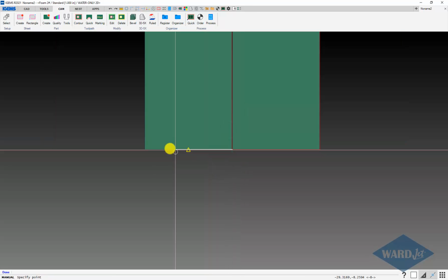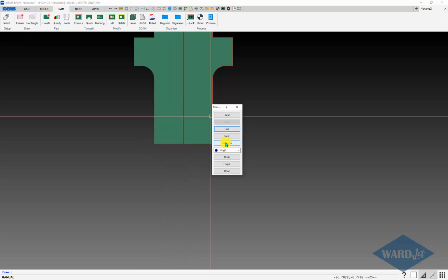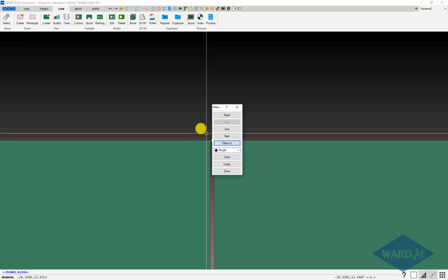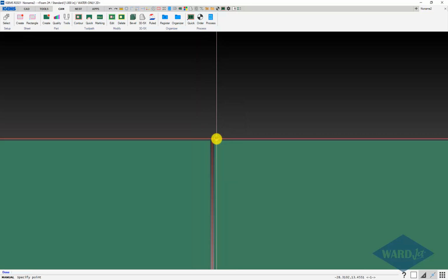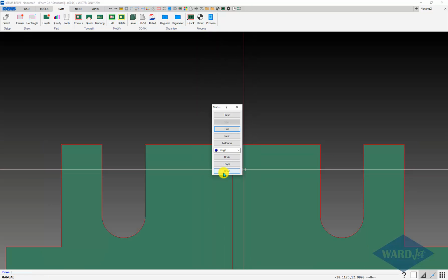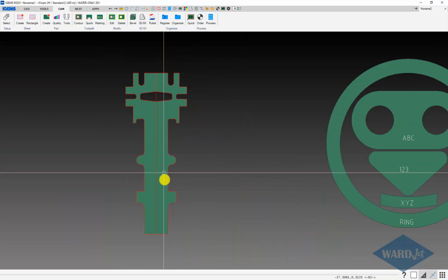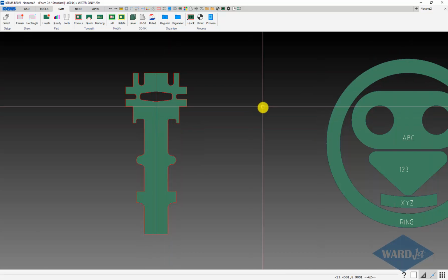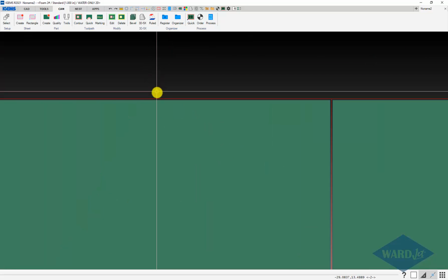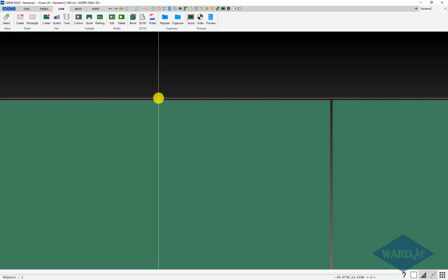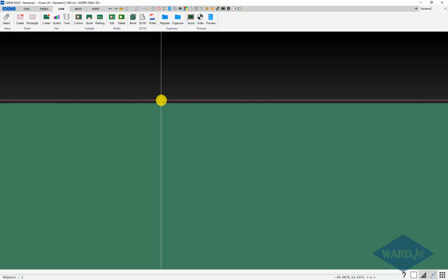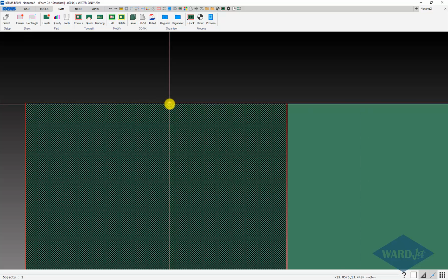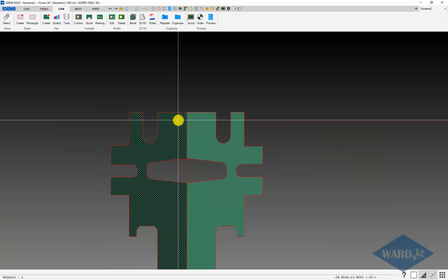and then we'll do a line, so I'll just go over to here, and we'll do follow to again, follow to up here, and then I'll do another little line here and make sure I cut all the way across there. So now I've got that nice toolpath on here. Essentially do this all in one pierce. Now right now this toolpath is not connected to the parts. If I zoom in, click on the toolpath, see when I click on that, it just selects the toolpath and not the part. Conversely, click on the part, selects the part and not the toolpath.